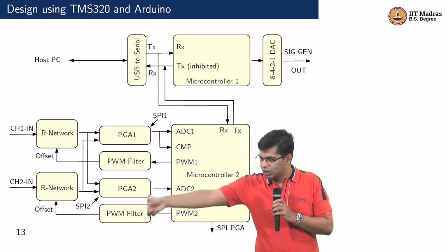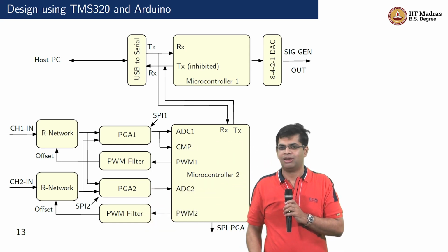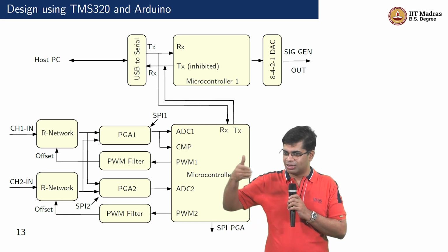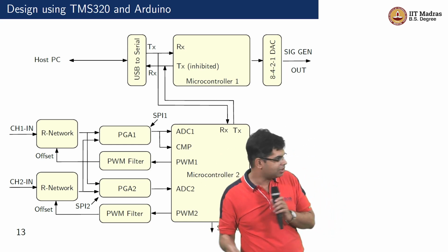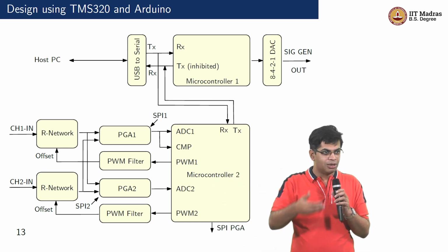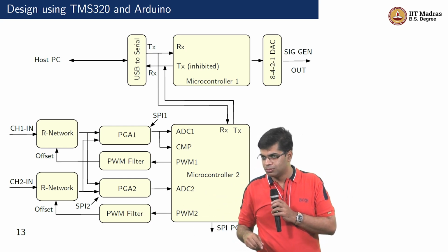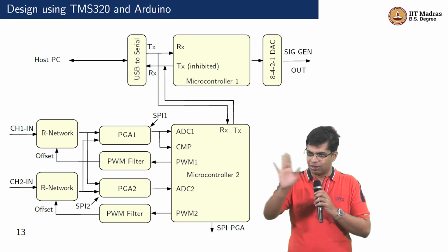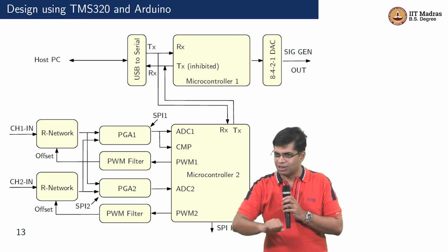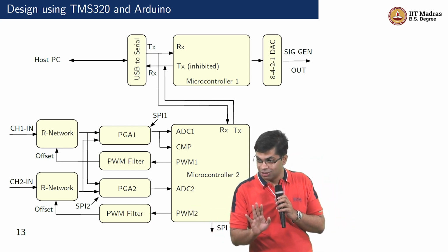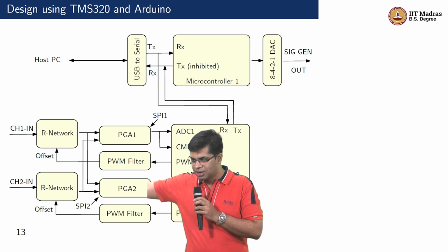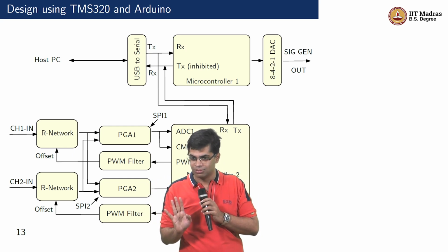We'll do the layout in KiCad, and then we print out that pattern onto this glossy paper, not toner paper, the paper that you use for color printing, photo paper. Use the photo paper on a laser printer and keep the toner on high, so you get the mask made in black. Flip it, put it onto your PCB, and iron it with a regular steam iron. It works. You can do 250 micron, that is quarter mm tracks with that, no problem. You have to be careful, that's all.